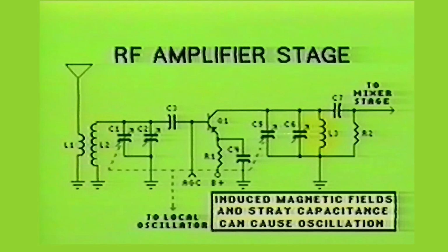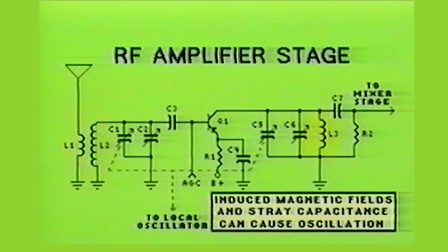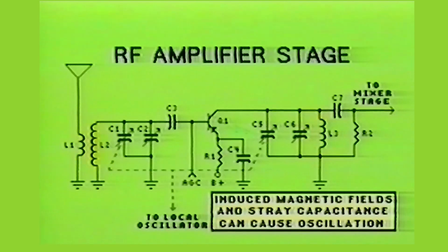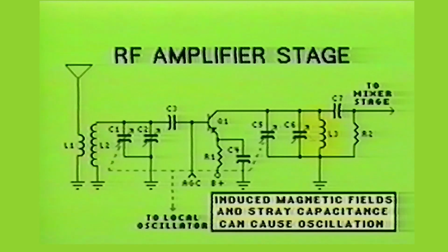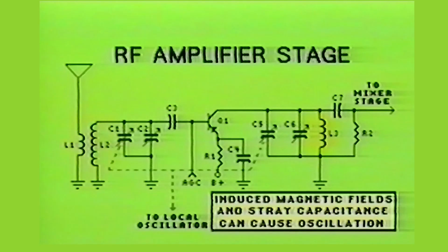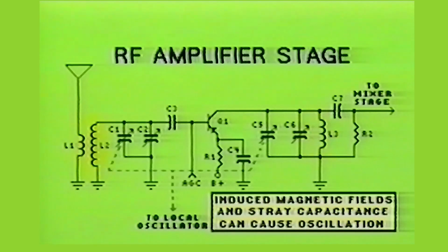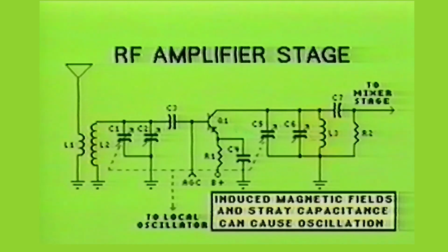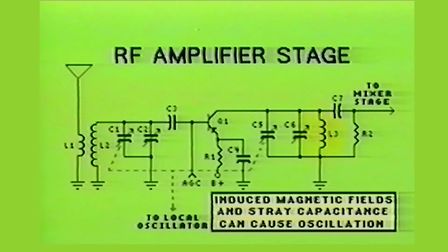When a component is replaced, its leads must be the exact length as the leads of the faulty component, and the new leads must be set back to the position of the original component. This is so important that many manufacturers often issue instructions on how to dress the leads for the new component. Any components which are replaced must be replaced with the exact specifications used in the original component. Even something as simple as moving a component, like a capacitor, to the side for the purpose of troubleshooting could cause the circuit to oscillate. Next, we will examine a typical FM mixer oscillator stage.